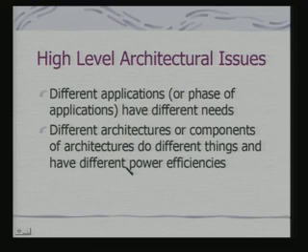And the other point that we have seen is the relationship of power consumption and efficiency with voltage. So, depending on computation needs, can we play with voltage and frequency? All these issues therefore have to be looked at in an integrated fashion for the purpose of having a power efficient architecture for embedded systems.